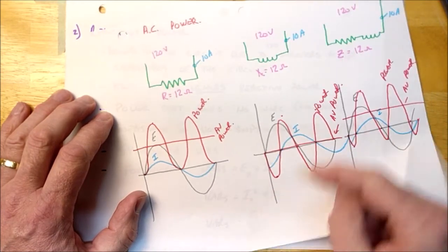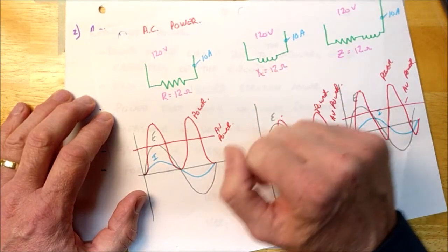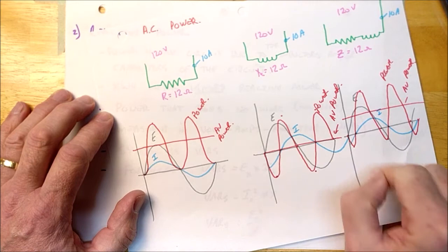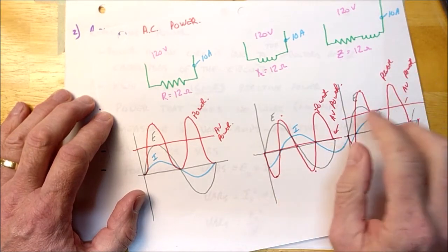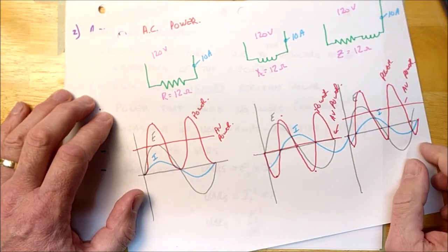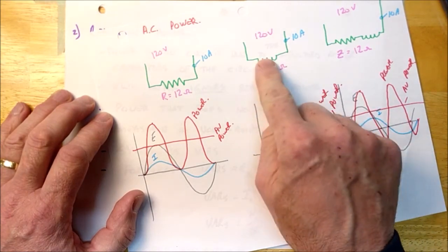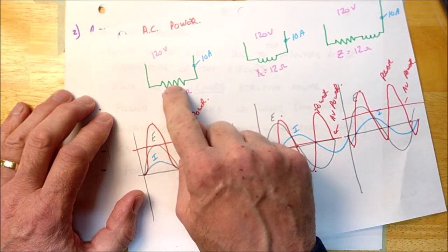students who've said to me before, listen, I'm going to put a giant inductor in my heating duct. It's going to draw 100 amps all day long. My meter's never going to move, and I'm going to heat my whole house up with it. Well, you can't do that because this thing is storing energy. It is not using energy like this thing does.